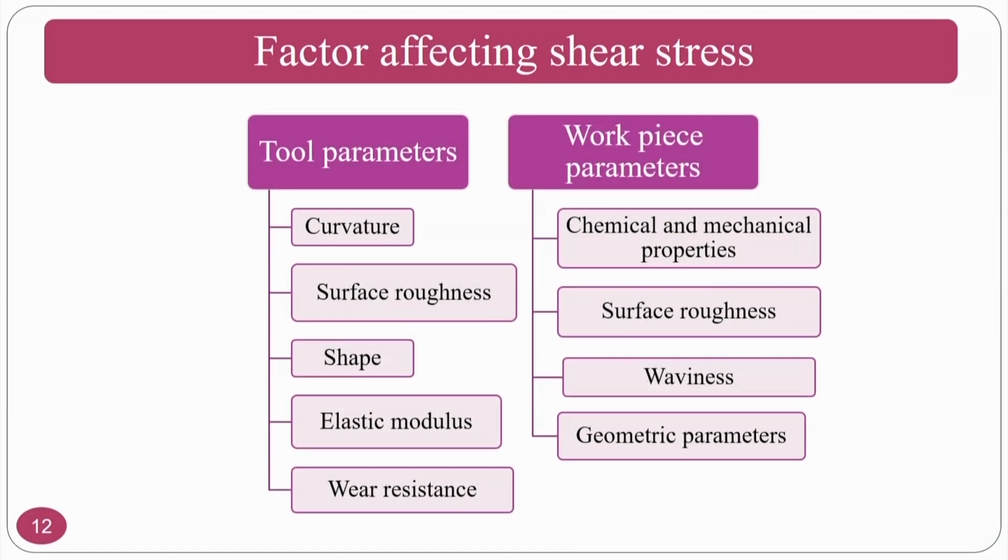So, the next set of factors affecting the shear stress is the tool parameters. Okay. The curvature: normally, spherical curvatures are the common curvatures. If the surface is like this, what will happen? The workpiece also gets a bad surface finish. The shape should always be maintained precisely, and the elastic modulus, you should have the appropriate elastic modulus that you require for that particular process, and wear resistance.